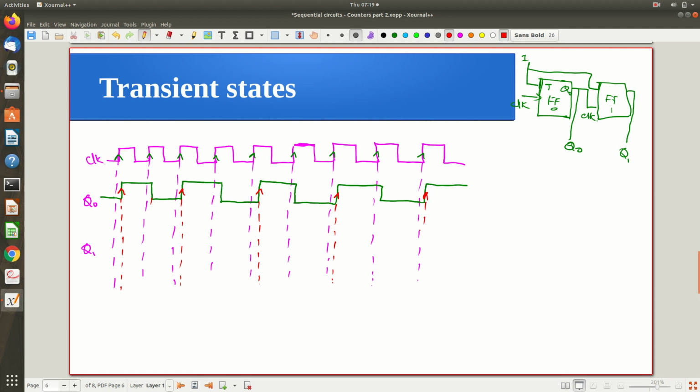Okay, so this is where we are trying to see the behavior of the output wave, Q1. And as usual, this Q1 is continuing in its low voltage, and immediately when it is getting the triggering, it is supposed to toggle, right? But again, as I said to you before, there will be a small delay. It's not going to trigger immediately. Instead, it will proceed for some time. And why this delay? Because of the delay of that particular flip-flop.